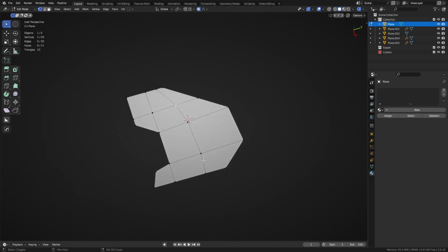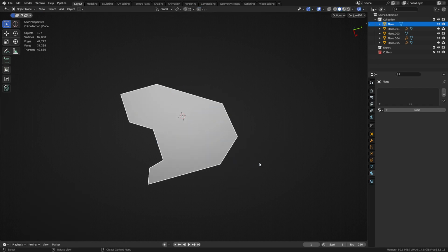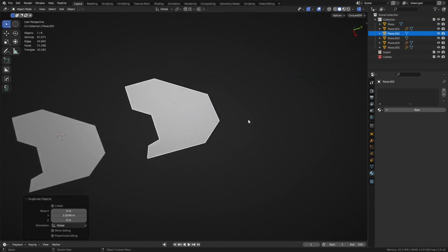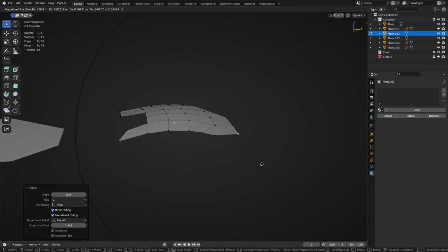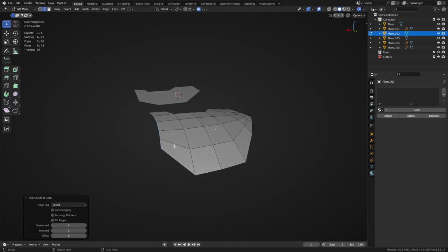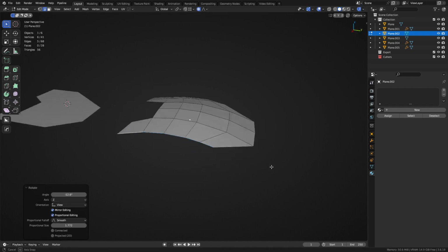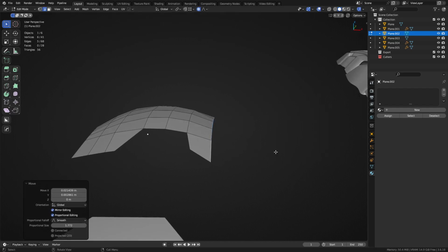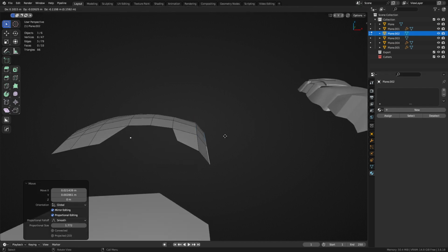So there's actually a trick to this. You need to deform this one and it needs more resolution, generally speaking. So you're just going to res it up by adding some loop cuts, something like that. Now you can deform it a lot easier. And we don't do the extensions just yet, right? Like the edges here. We do them after we get the shape that we want. So we can do proportional edit, the lattice modifier and all that fun stuff if we wanted.